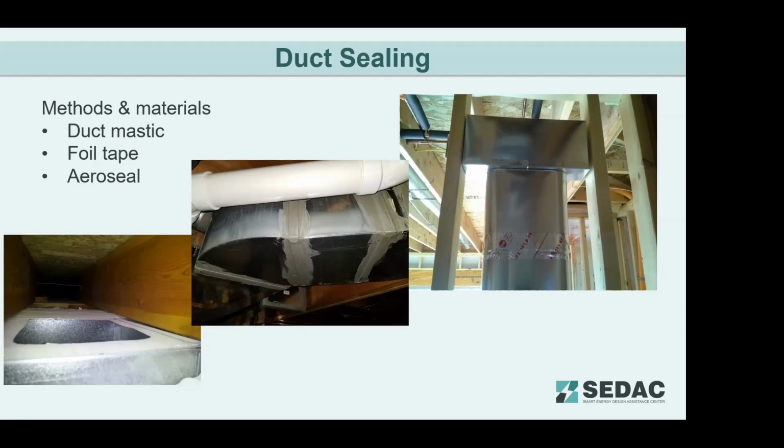And then if you haven't heard of AeroSeal, that's a company that can come in and actually seal the ducts from the inside of the ductwork by injecting a bubblegum type of aerosol mixture that can seal gaps, I think up to 5/16 of an inch. That's a pretty small gap, or a pretty large gap that it can seal. But a little bit more expensive to seal ductwork that way, but it does a phenomenal job as well.